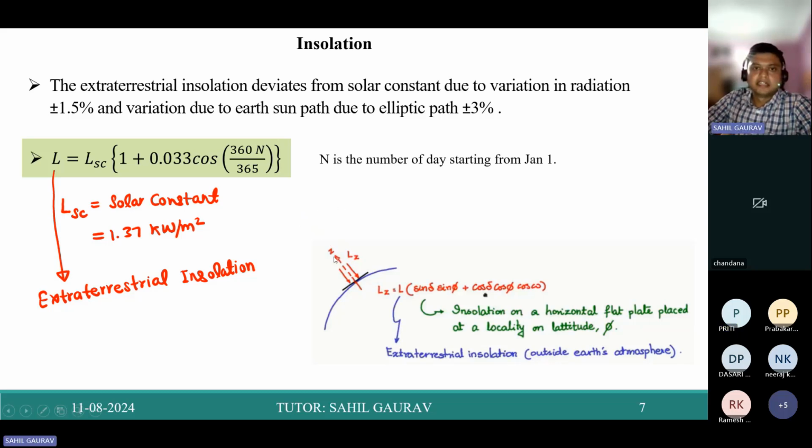If you are having this diode across each PV module, then this cut-in voltage should be lower than your PV, like 0.2, 0.3. So it makes it costly to make that type of diode. For making a diode with a cut-in voltage of 0.2 or 0.3 volt, that makes it costly. So generally we have diodes with a cut-in voltage of 0.7 volt like that.